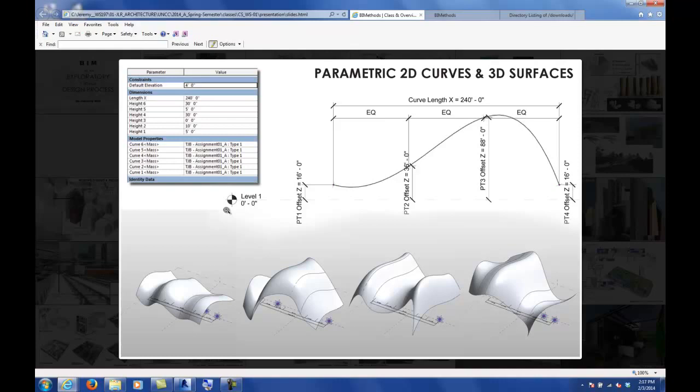And the parameter exists not only in BIM, but it exists in other programs like Grasshopper and scripting and all these other computational programs that you've been using in the college. A parameter is basically just a container of information. It's something that can hold any kind of data. It can be dimensional data. It can be a yes, no kind of checkbox. It could be text. It could be anything like a website. But essentially, it's a name that's given to a container that then has a piece of information that either drives the design or starts to report on the design.